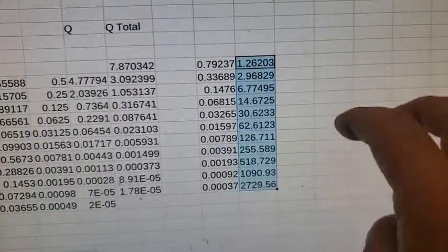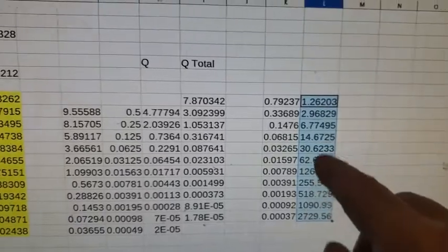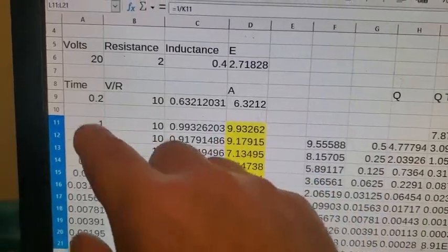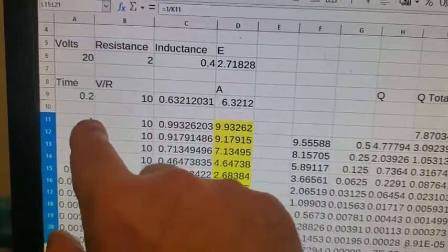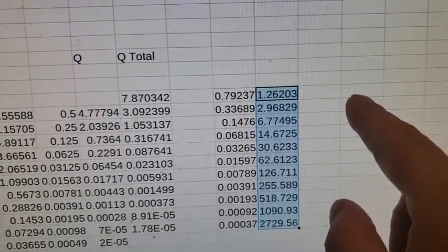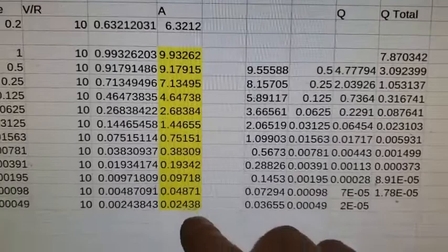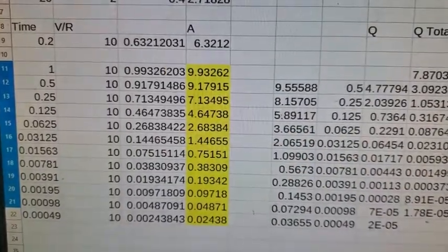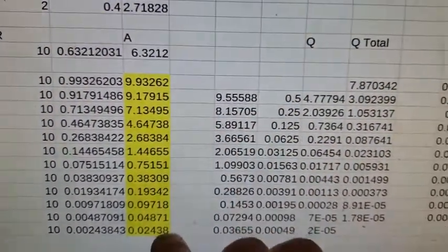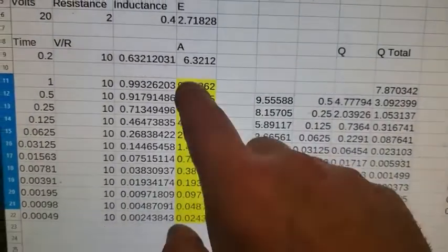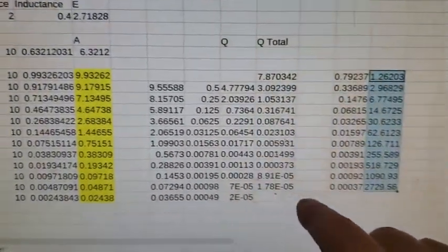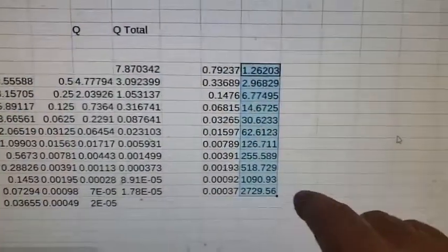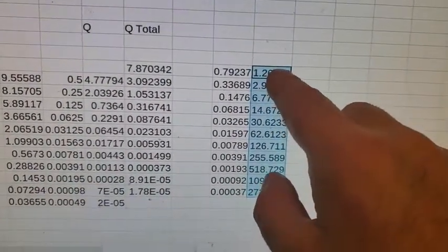So if you're looking to gather the inductive spike, this is more than 2,000 times more efficient than just charging the coil to 5 tau times. Now, of course, this will give you the strongest inductive spike. This inductive spike here, let's see, 0.02 versus 9.93. So it's on the order of 500 times weaker. However, for the number of coulombs of charge you expended to get this magnetic field strength, it's more than 2,000 times more efficient than here.